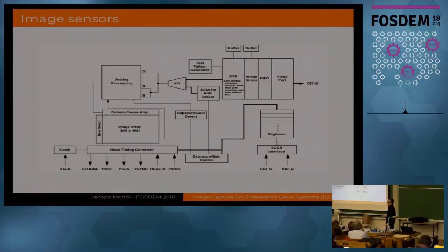And the raw image, which is called the raw matrix, goes through what is called the analog processing part, which makes the transformation to different color encoding schemes, the ones that we program using these registers. Depending on how smart the sensor is, you can have advanced features here, you can have DSPs that perform transformations and advanced algorithms like auto white balancing, auto exposure, and things like that.